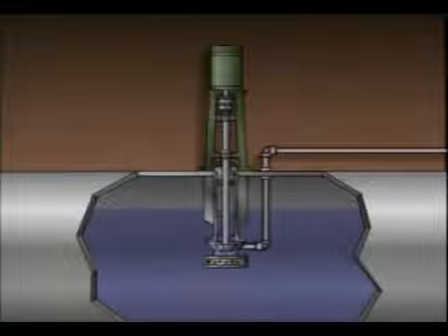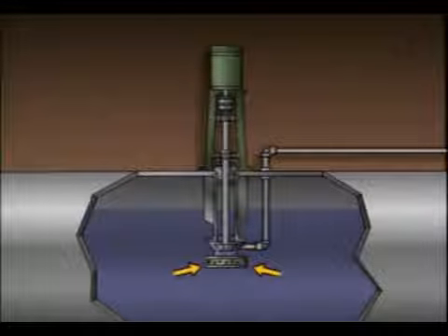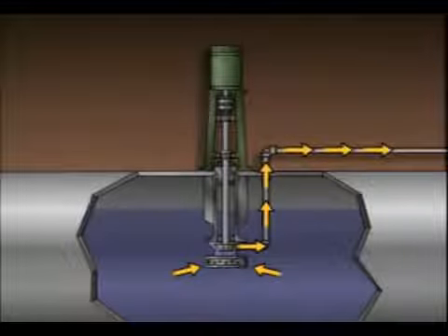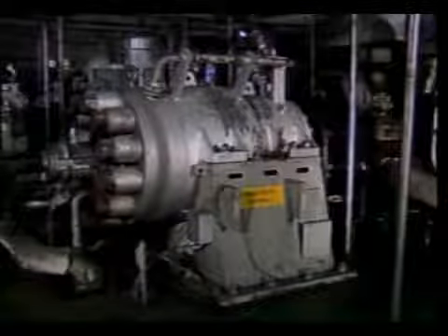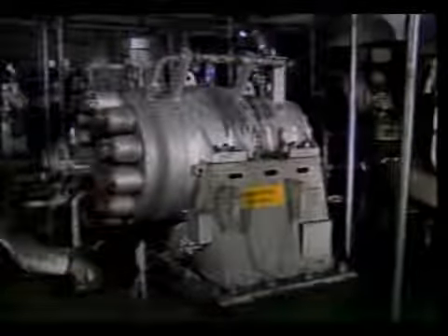During operation, liquid is drawn in through the suction and then pumped through the discharge piping, which extends up and out of the tank. All centrifugal pumps work by creating a centrifugal force. This force moves the liquid through the pump and increases the liquid's pressure. In applications where large increases in pressure are needed, multi-stage centrifugal pumps are often used.